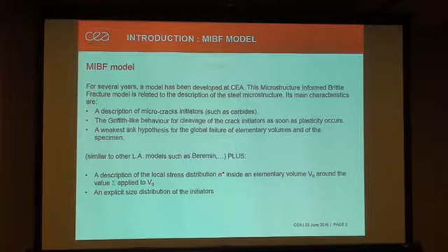Its characteristics are a description of microcrack initiators, such as carbide, a Griffith-like behavior for the crack initiators, and a weakest link hypothesis.